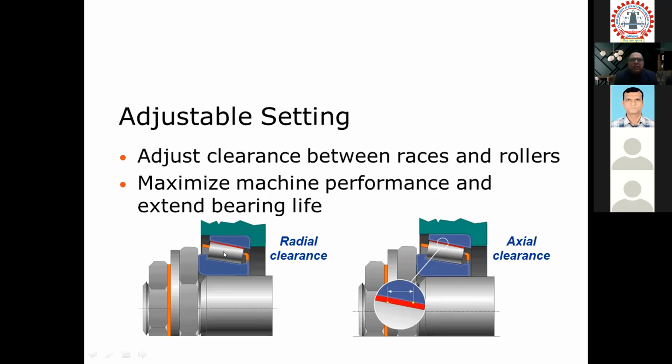The third question is about maintenance. So yes, maintenance is very difficult. And in some cases, it depends a lot on the experience. But in many cases, bearings or the housings are designed in such a way that you are able to view the bearing, or you are able to open at a certain interval. Just to give you an idea, there are very large bearings, say about 1 meter or 2 meter diameter, and they are available in two halves. So you can easily install and remove because they are in two halves of 180 degrees each.